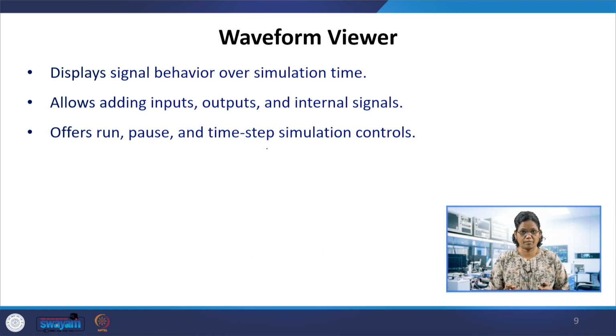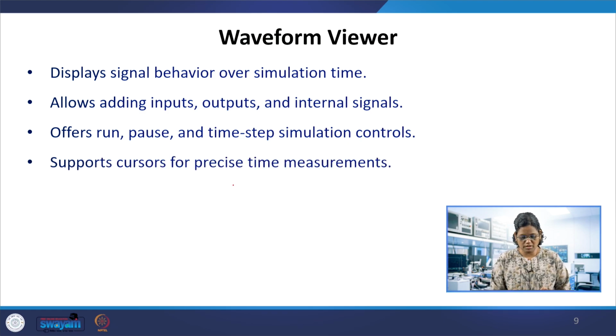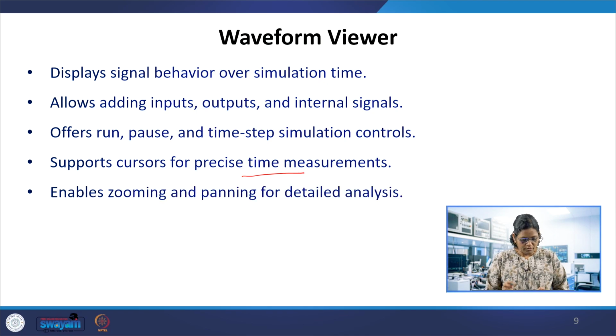What is the time step? We can specify that, and the simulation can be done with time steps as well. It supports cursors for precise time measurement, so we can place the cursor and measure the time duration for which a signal changed from 1 to 0, or what the changes are. It also enables zooming and panning for detailed analysis, so we can view a particular portion of the waveform and see the details of the signal.